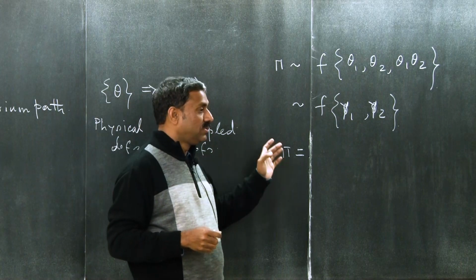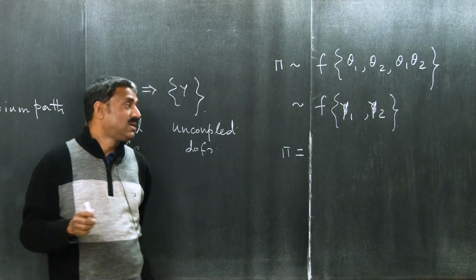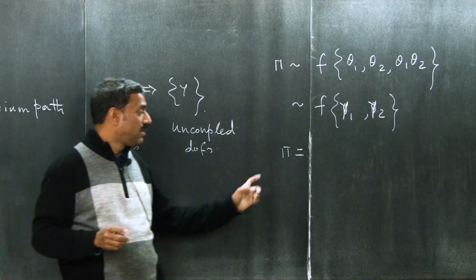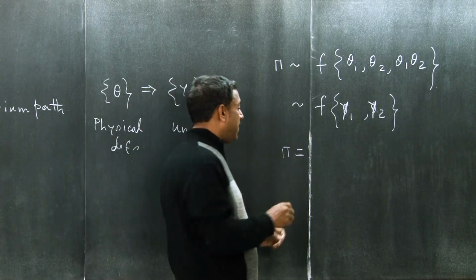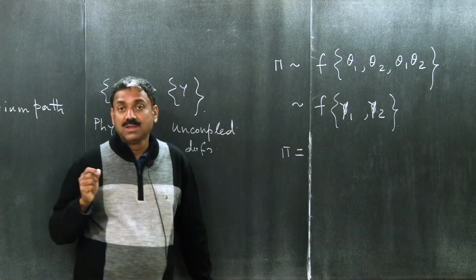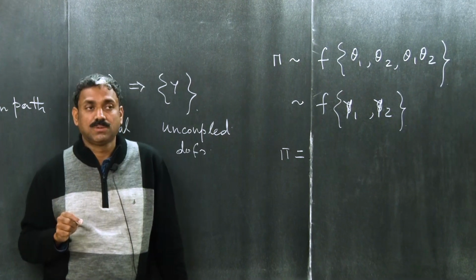And if we do not require to find out in that case the Hessian matrix or a determinant or principal minor, rather by looking into the sign of the coefficients of the potential energy function, we can comment on the nature of the equilibrium, whether it is stable, unstable, or neutral.